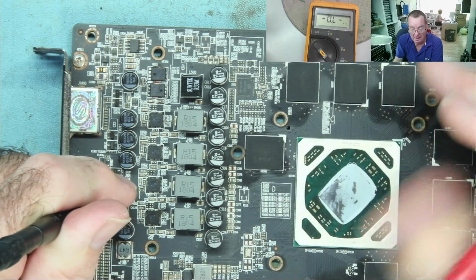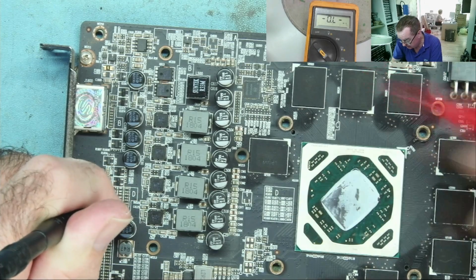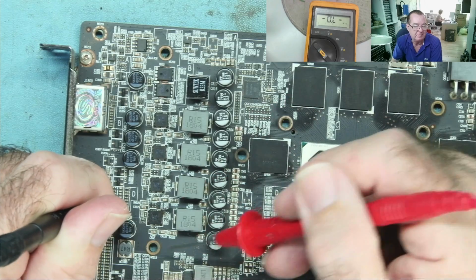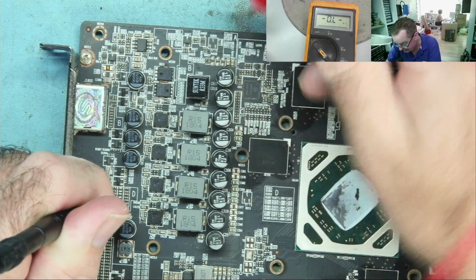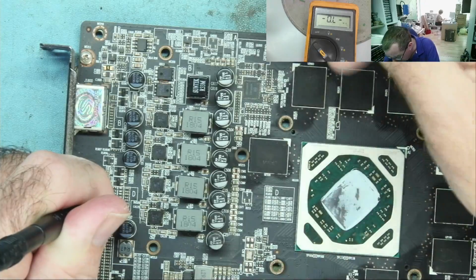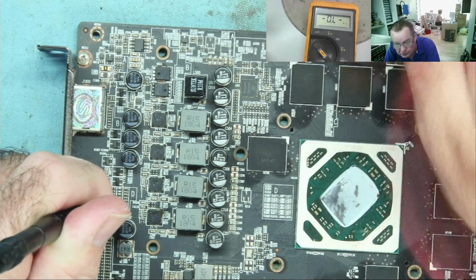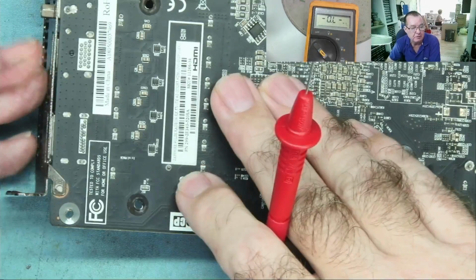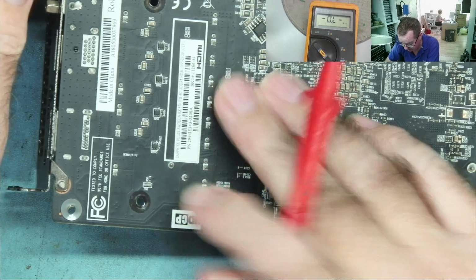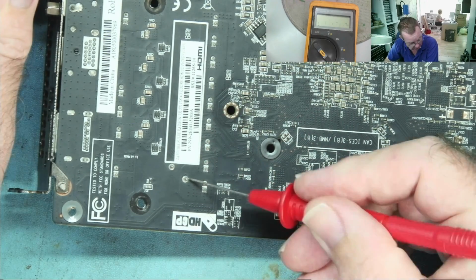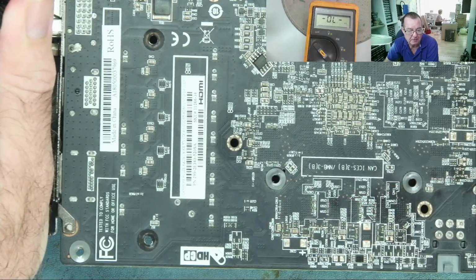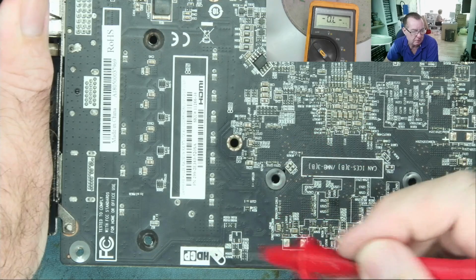So that is actually, I'm sure, okay. We can compare with the other one. So if this is RAM and these are for the GPU, and we've kind of said, well, probably 1.8 and 0.9. This is probably the memory controller. Let's have a look at it. This one has actually got no legs on this side. It's going through the board, so it's not a surface mount one. What's this one read? About 17, okay. This one's 17 and the one was 33. This is probably the memory controller.